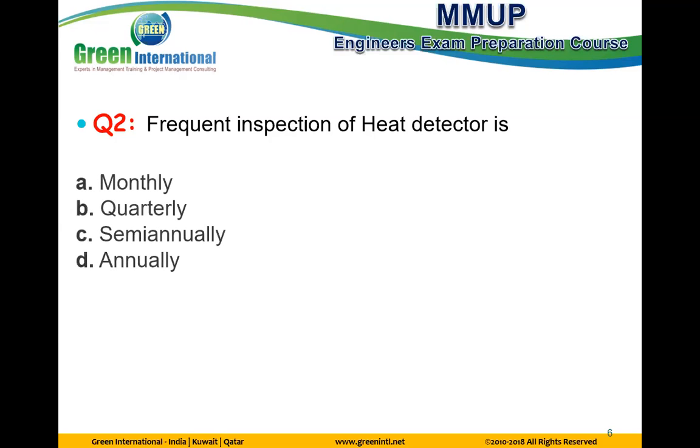Frequent inspection of heat detector. Monthly. No, semi-annually. Frequent inspection for almost all alarm systems is semi-annually, and testing is normally annually for alarm systems. We will see here some special and specific questions. The answer is quarterly or monthly. Maybe monthly is one question or something like this.